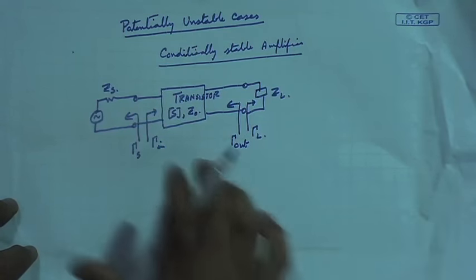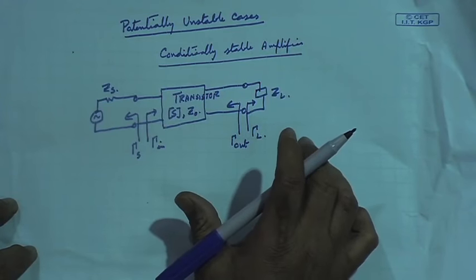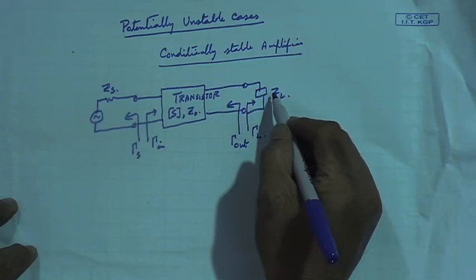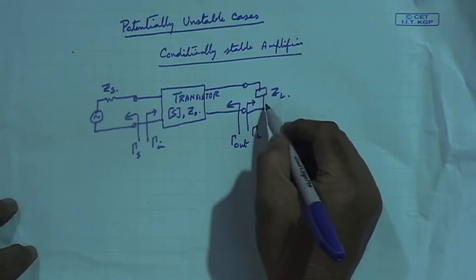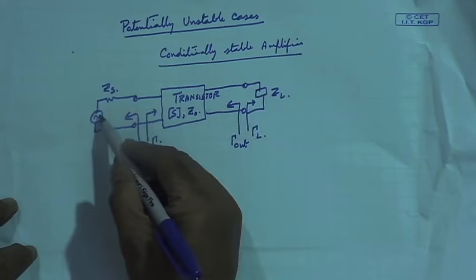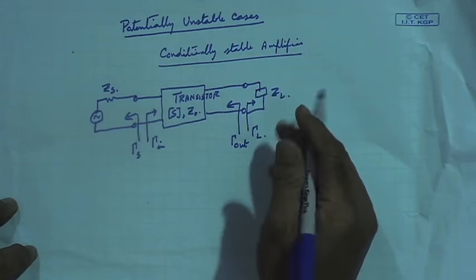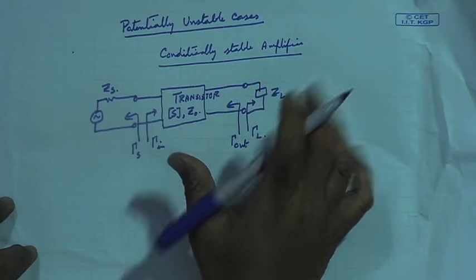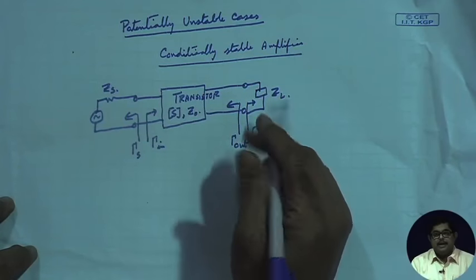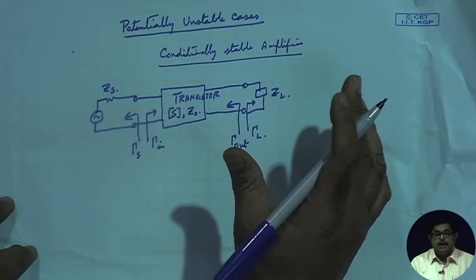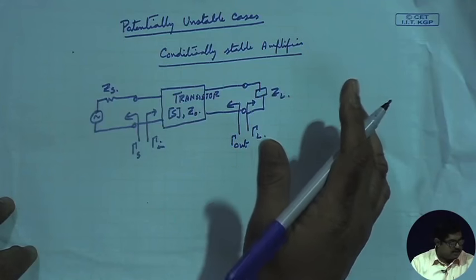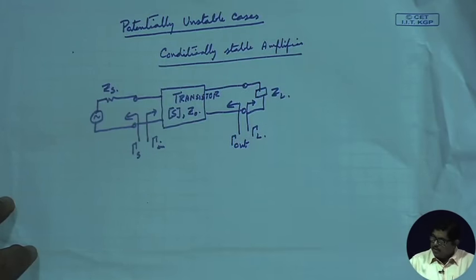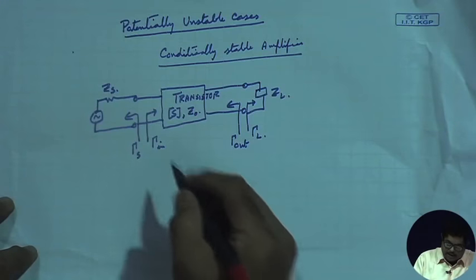We have seen that transducer power gain will give us the actual value of the power that is dissipated in the load divided by power available from the source. That ratio, that means in the loaded condition, the full system's power gain, is the useful criterion which we will try to maximize finally and achieve an amplifier design. Now, last day we have seen that